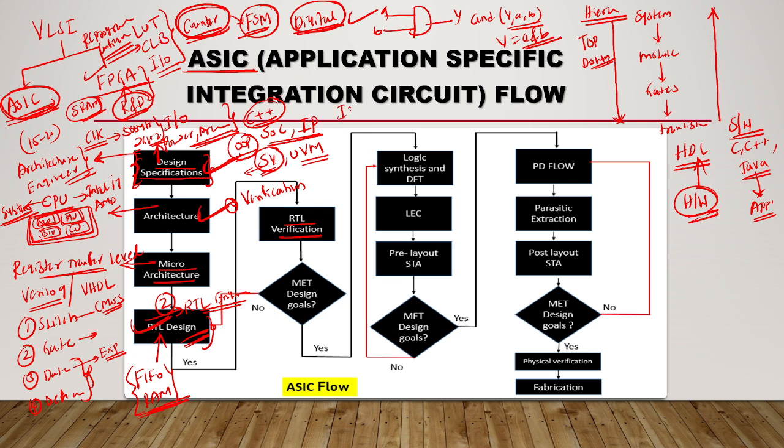So an SV test bench is robust. Suppose you are writing for I2C, separately you need to write for UART. So it is time consuming, so that's why you need to go to UVM, that is Universal Verification Methodology. This is not a language, it's a methodology. You are using SV in the UVM. Suppose you wrote the test bench for I2C, then by using simple methods and some changes you can write the test bench for UART. So that flexibility is there in UVM.